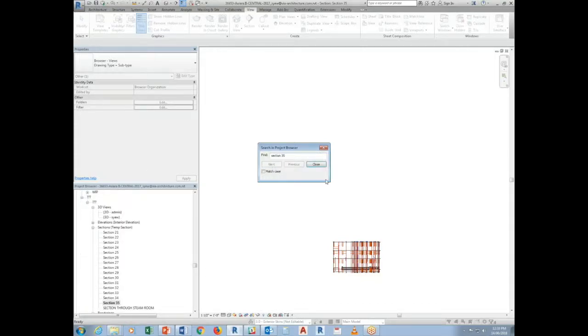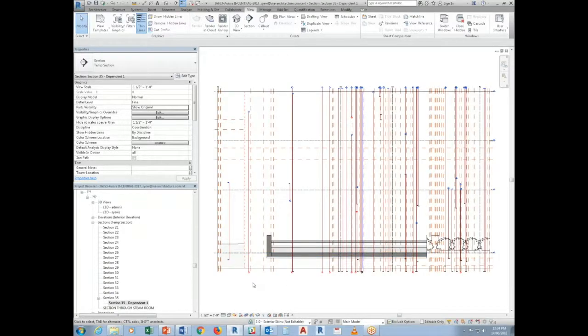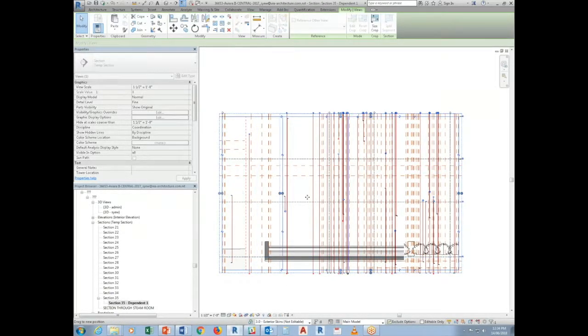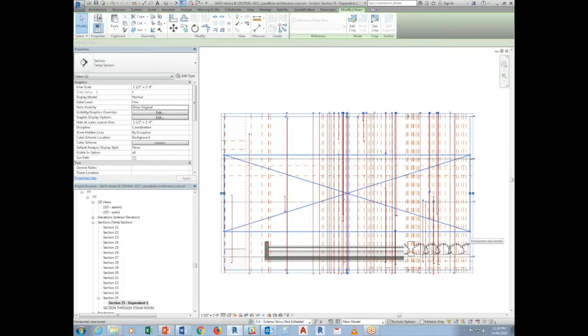Next. Okay. So most of the time what people do is that they just say, okay, I'm going to duplicate as a dependent. Now what happens is that when you start doing it, sometimes your dragging cursor will not work. Okay, this has happened quite a bit. This time it works fine, but you will encounter where when you try to drag this, it would just get stuck in that location. It would not go. Okay, so how I fixed it was that you kind of have to remove that.